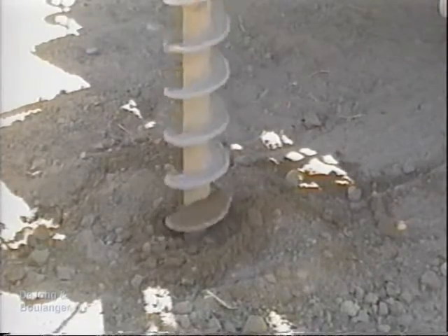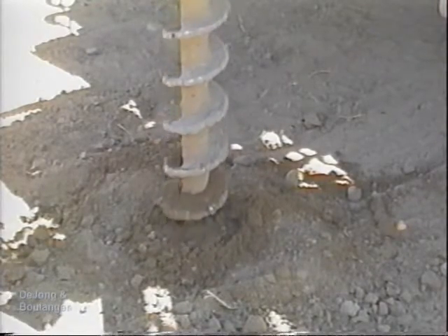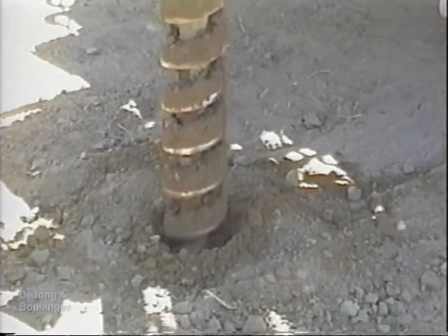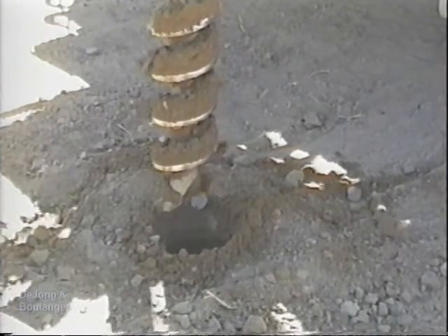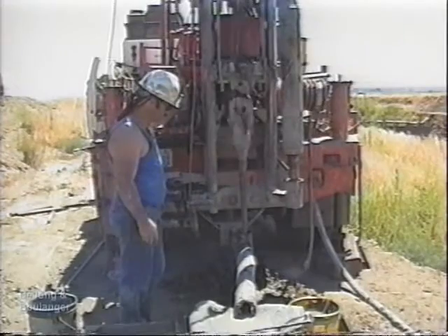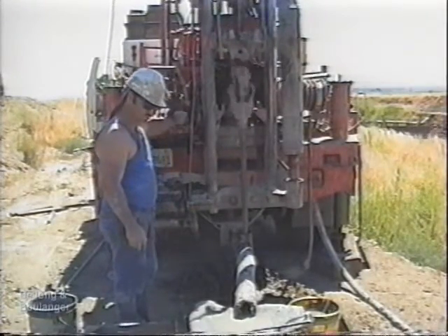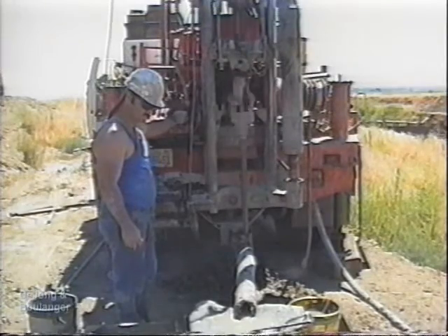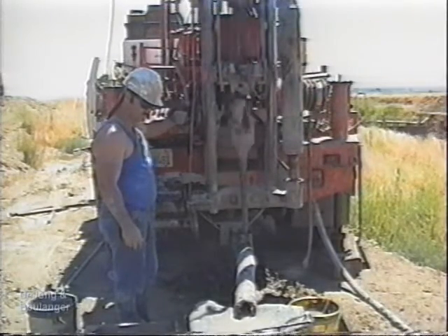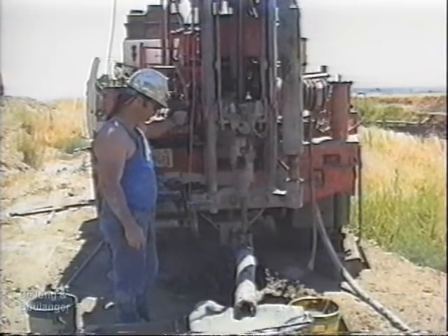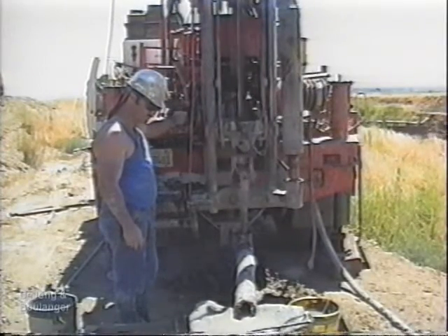It is recommended that the diameter of the borehole be 4 to 5 inches. As the diameter of a borehole is decreased, the penetration resistance is likely to increase. Side discharge bits should be used when rotary drilling because the jetting action of a face discharge bit disturbs the soil at the bottom of the borehole.